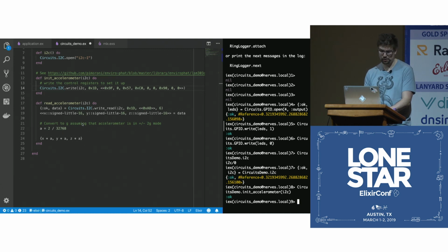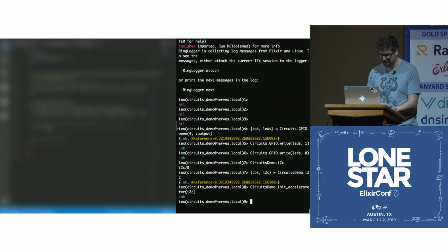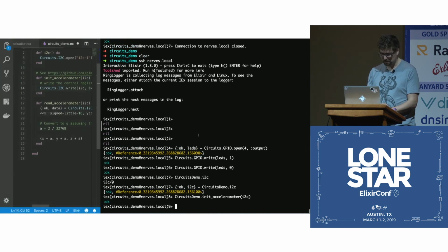This just does a conversion here because this accelerometer is in 2G mode, and a little math for it. You can read more about how accelerometers are set up later. But essentially, we want to see this calculated, where we'll get a positive value up to +2 or down to -2 Gs for this.